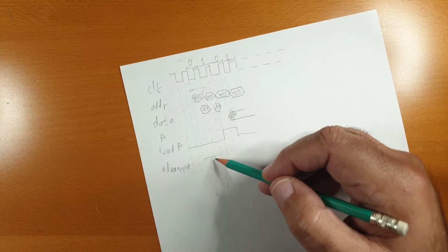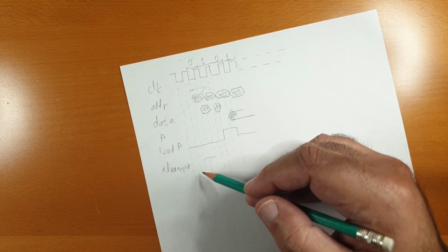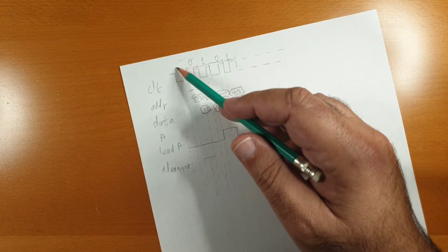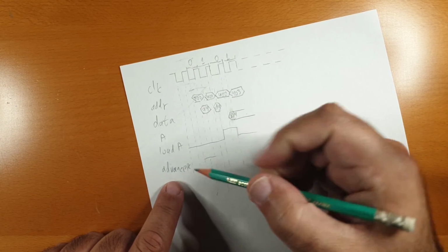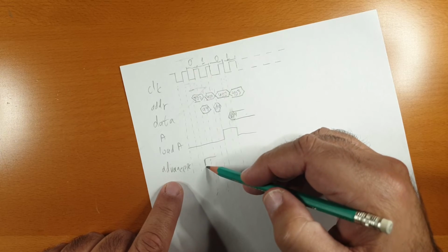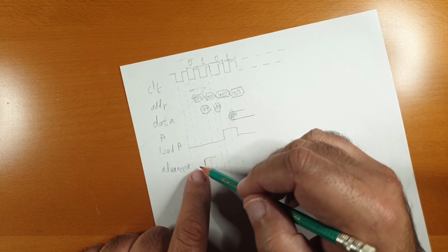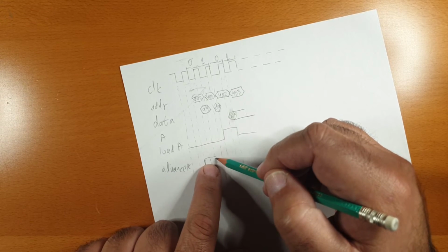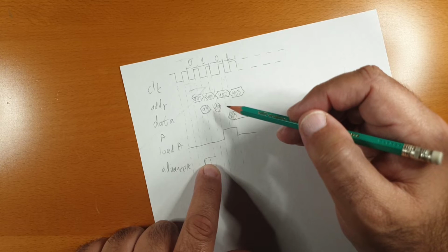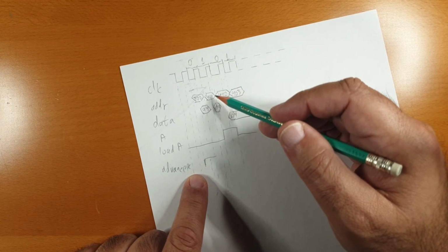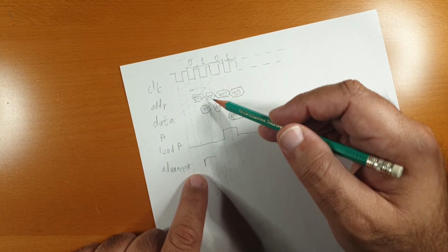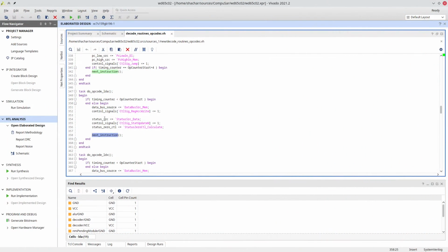But for it to be high during cycle 0 of this opcode, it needs to be set high during the last cycle of the previous command, because this control line is latched on the falling edge of the clock, which means that we're setting it high here in order for it to latch here, in order for it to take effect here. So when we control the program counter, we actually need to be 2 cycles ahead rather than 1. So a beautiful, beautiful code here, all sitting together in harmony, affecting the control signals altogether, doesn't apply when the program counter is involved. When the program counter is involved, we need to actually think ahead. We need to be one cycle before the rest of them.